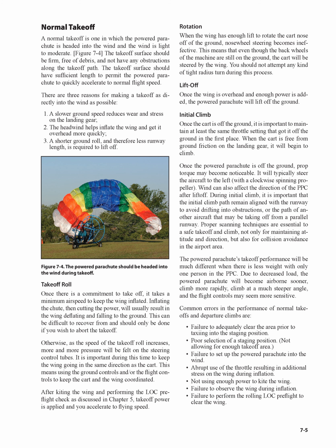Liftoff: once the wing is overhead and enough power is added, the powered parachute will lift off the ground. Initial climb: once the cart is off the ground, it is important to maintain at least the same throttle setting that got it off the ground in the first place.